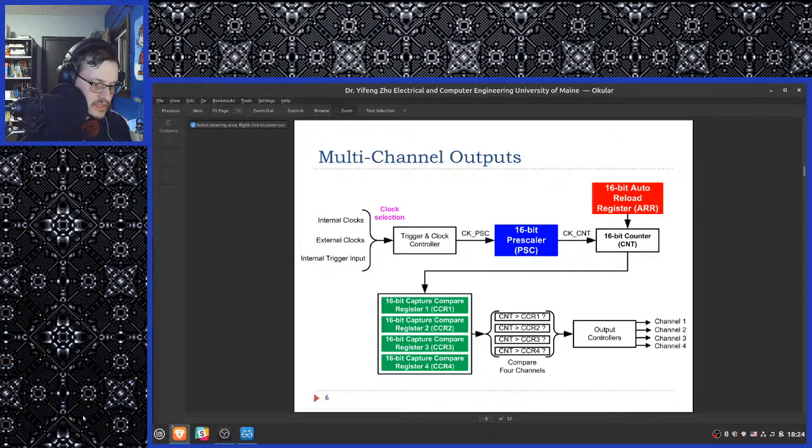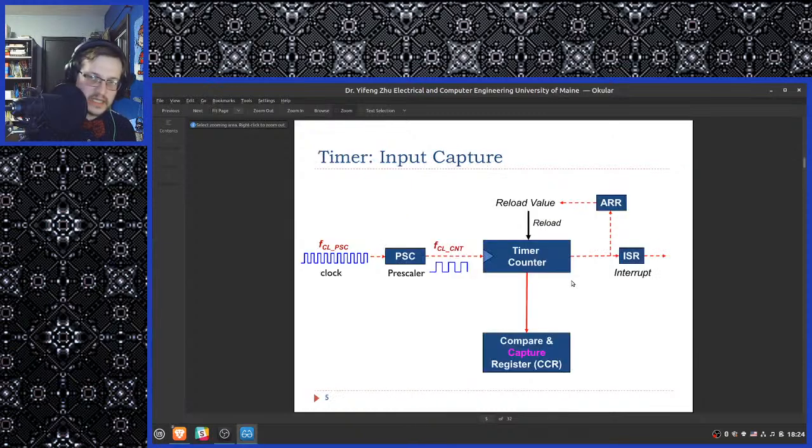The counter and constant aren't compared in the ALU, right? Correct. Those are being compared by circuitry contained in the timer peripheral apparatus. None of the operations going on here require the CPU, which is why it can time more accurately than the CPU, because the CPU doesn't touch any of this.